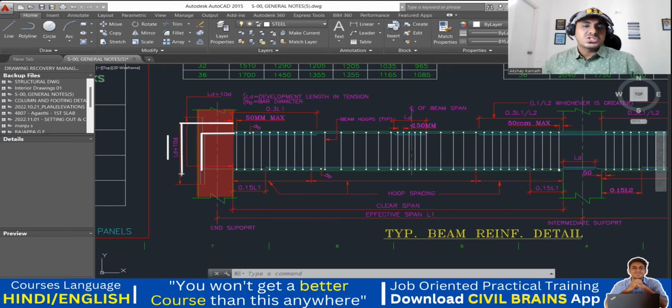If it is a normal structure, then it is only LD. If it is an earthquake resistant structure, and if you're following ductile detailing, it will be LD plus 10 times the diameter of the bar. Got it? For the top and even for the bottom bar also, it's the same thing. Bottom also, you have to follow the same thing like this. They mentioned it here. Understood? It's written here: development length in tension, dB is the bar diameter. Got it? Good.